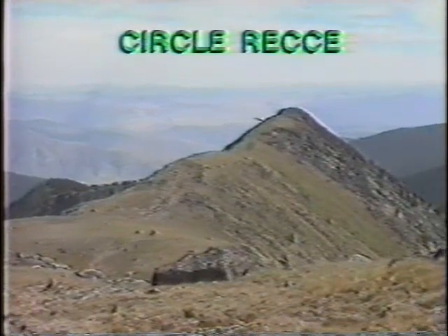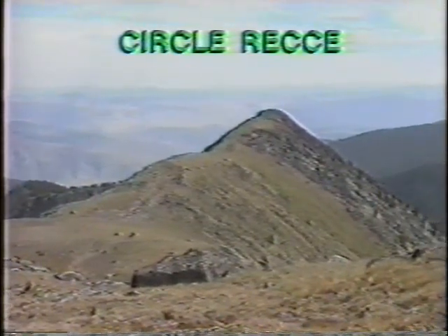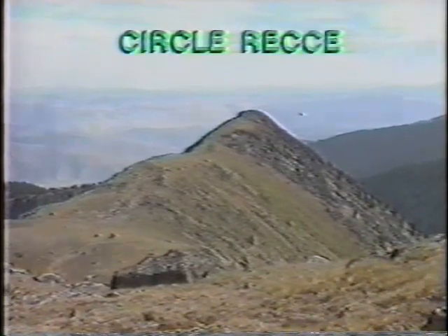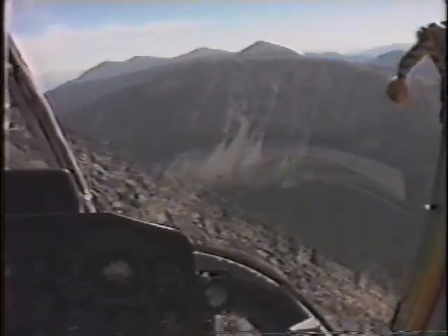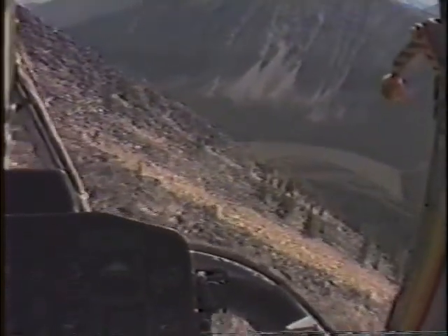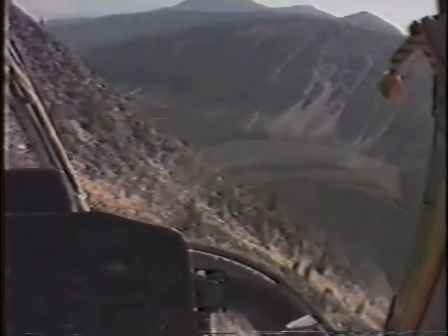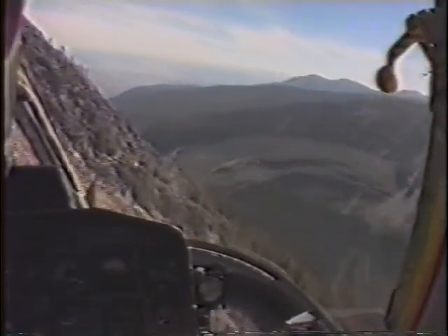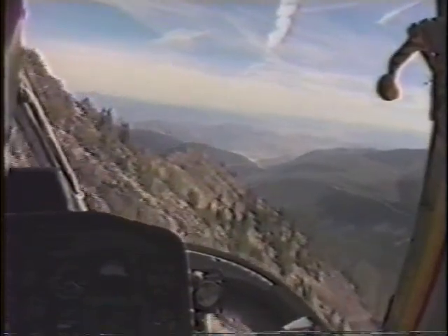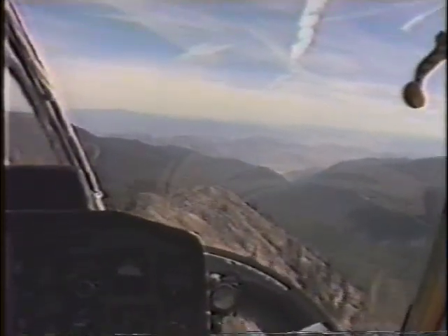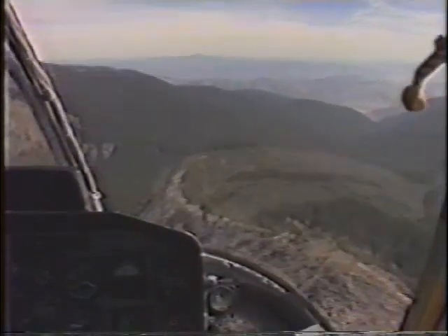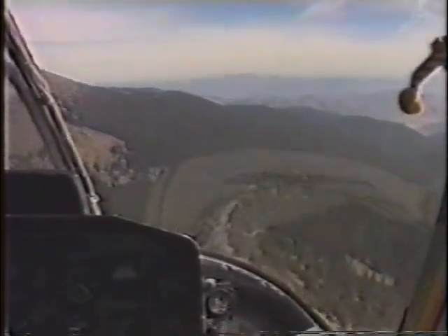It forces you to fly in bad air and makes you give up your drop-off for a large portion of your pass. In all mountain flying, you should maintain that safety valve, the drop-off area that you can head for just by easing in forward cyclic, losing altitude, but gaining airspeed and lift. Remember, all the power in the world in the form of collective won't keep a helicopter flying at this altitude in adverse downflowing turbulent conditions without sufficient airspeed.